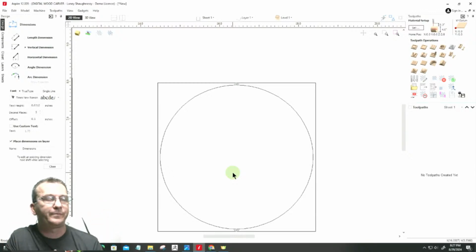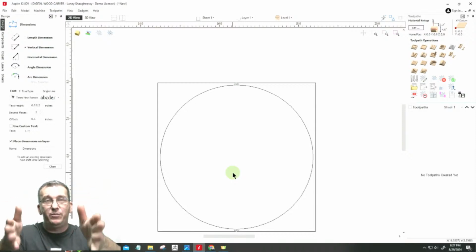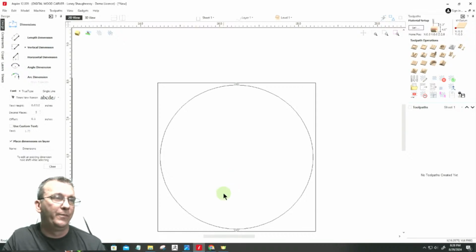No problem. That's fine. But it's not always that case. So if you're like, hey, I've got to have a 4" by 4" apron, whatever the case may be, then my blank needs to be at least an 1/8 inch bigger, 4 1/8 by 4 1/8, before it goes to the machine, before it goes to rounding and all.